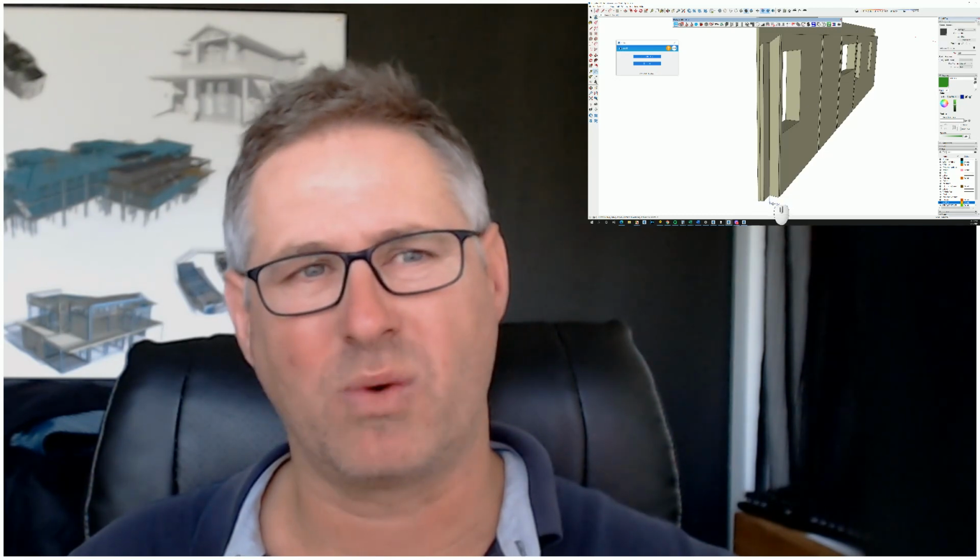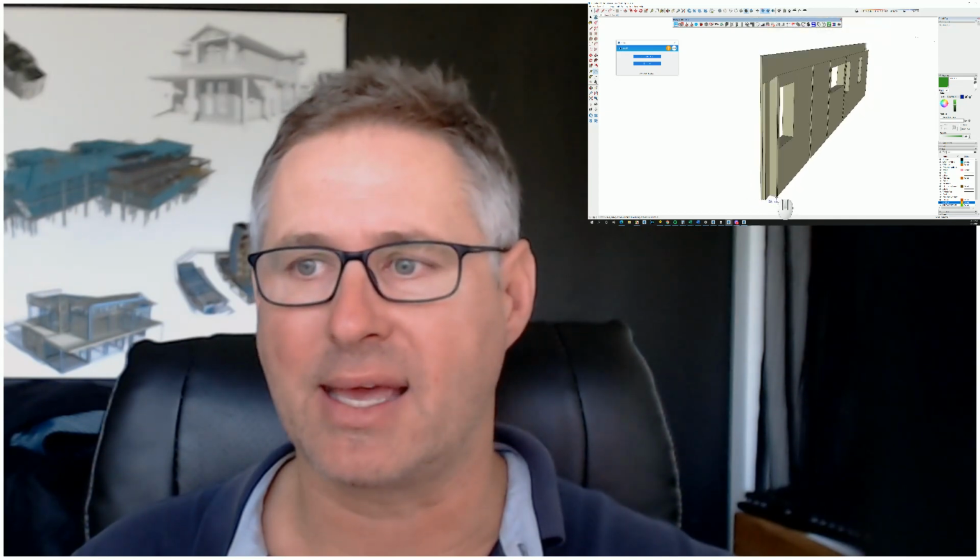So the first thing I need to know is my stud spacing or stud thickness. So if I choose a keyboard shortcut and go dimension here, that's telling me my studs are 155. It's an unusual size in metric. It's probably 140, or it could be that this is a level of insulation and it hasn't been attributed by ArchiCAD. Whatever it is, you can change your stud sizes and everything in PlusSpec, but we'll get onto that in a second.